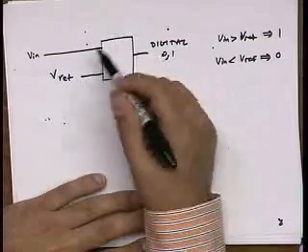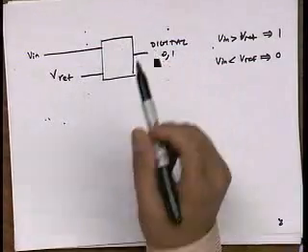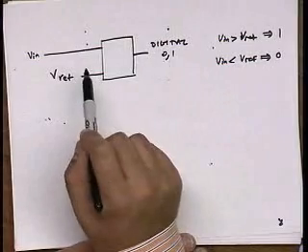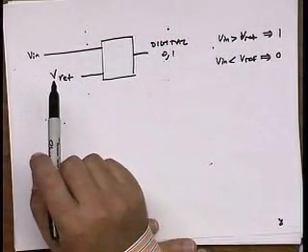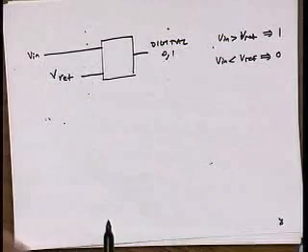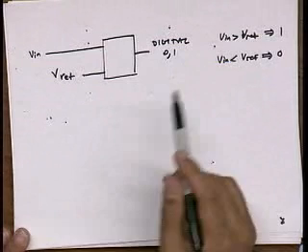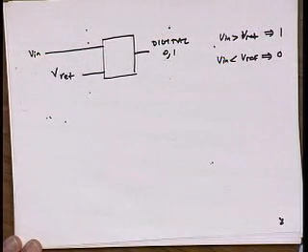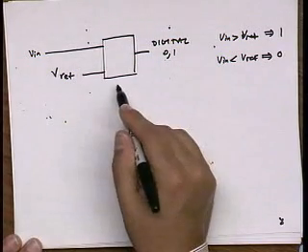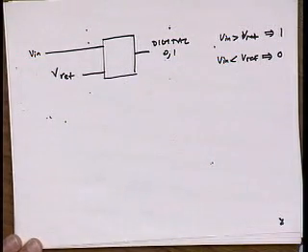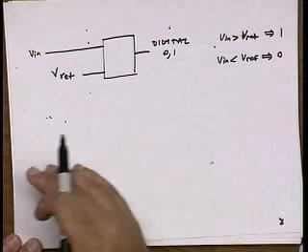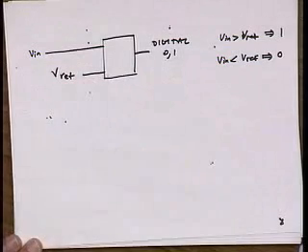It's also a very useful building block if you're building an A to D converter. If I'm building an A to D converter, the world's simplest A to D converter is I compare my input to a whole bunch of references, right? And depending on which ones are bigger, which ones are smaller, I know exactly where my input signal lies, right? That's a brute force A to D converter. It's called a flash A to D converter. I just have a bunch of parallel comparators and just observe when the input signal is no longer bigger than the reference. Maybe I'll draw a picture.